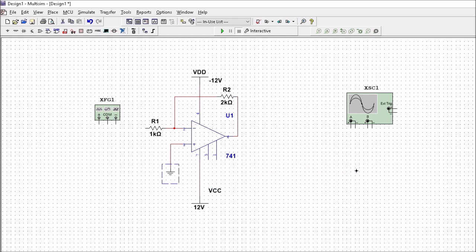The ground terminal here is going to connect to the negative terminal on the oscilloscope in channel 1 and on channel 2. We'll take our output and put it onto our B channel, that's our output there, and we'll take our input and put that onto the A channel, so that's our input there.